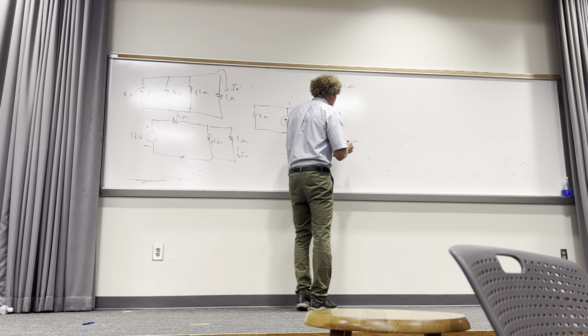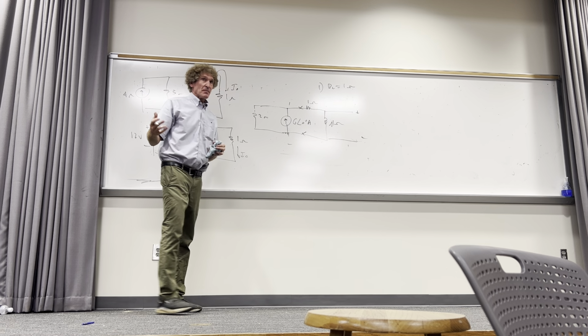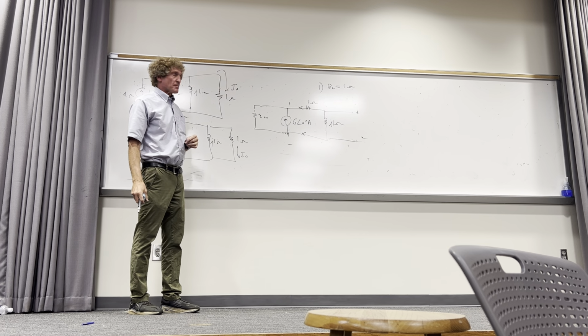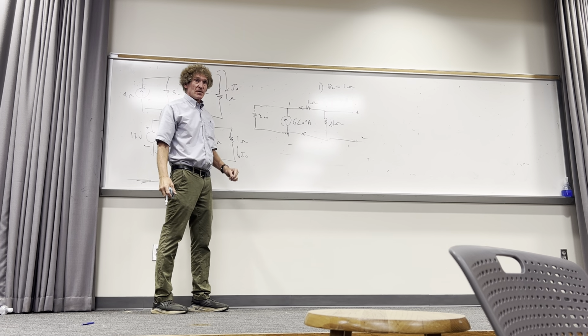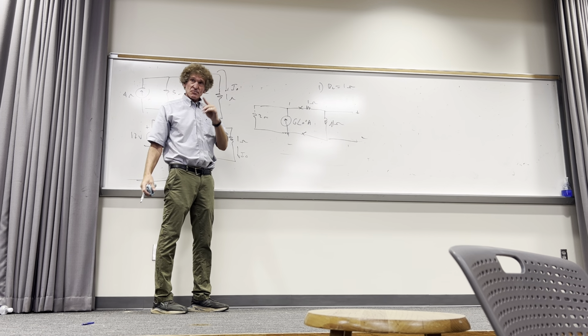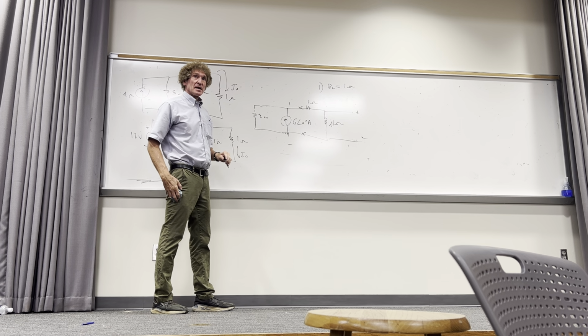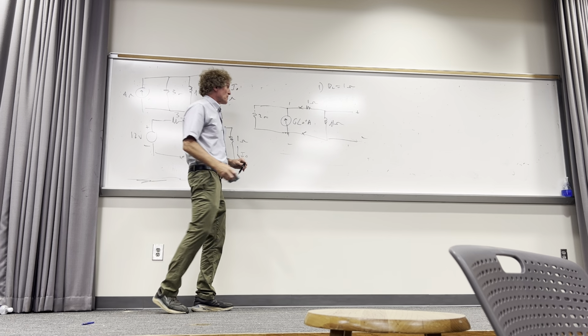Now I want this voltage, right? Just think of how many different ways we can get that voltage. What did I do before? The transform: a current in parallel with a resistance is a voltage in series with that same resistance. Do y'all remember that? Just watch this, you'll get it. So that's going to be 12 in series with 2.